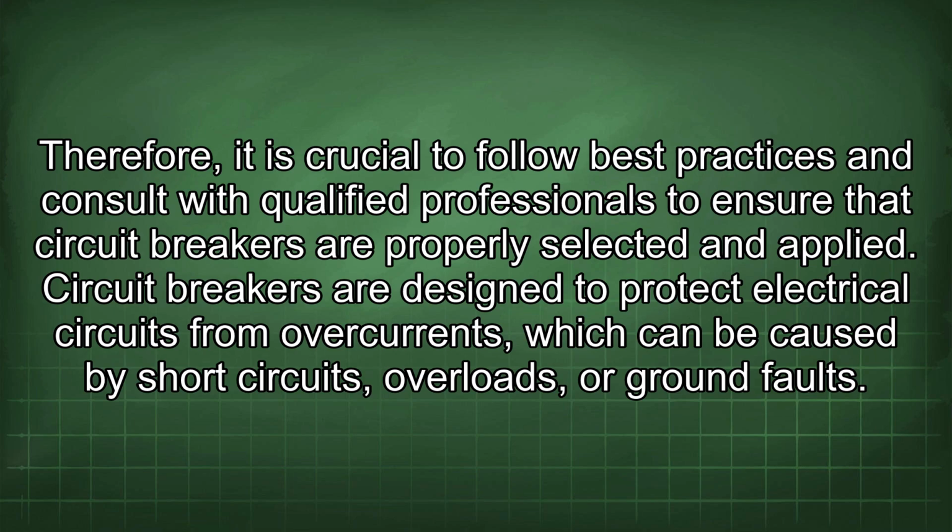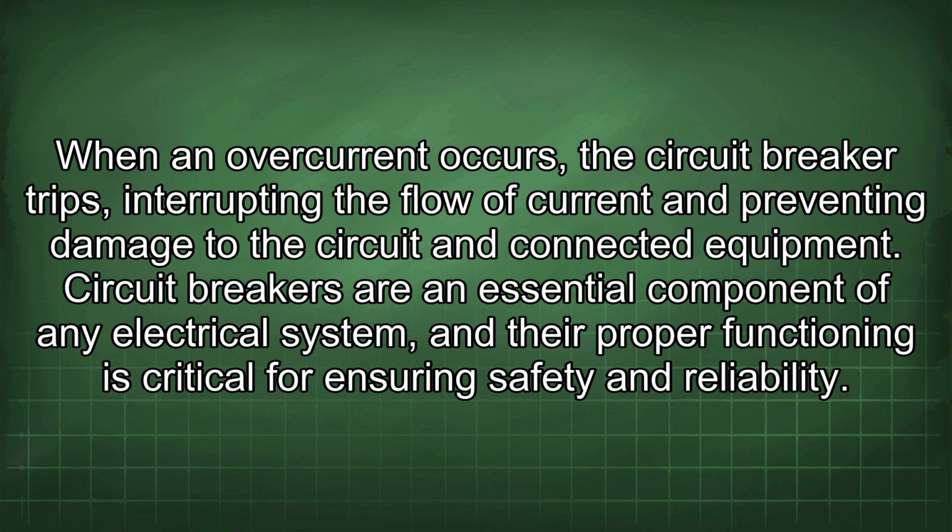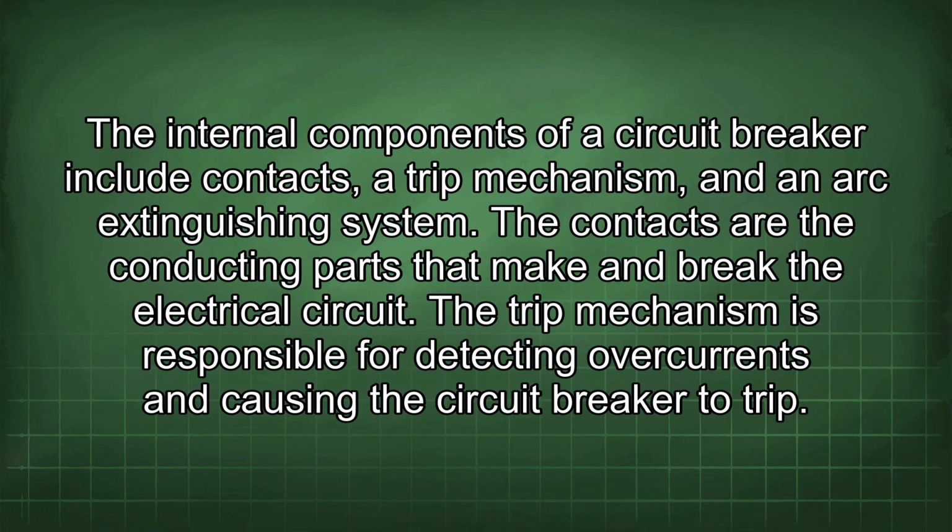selected and applied. Circuit breakers are designed to protect electrical circuits from overcurrents, which can be caused by short circuits, overloads, or ground faults. When an overcurrent occurs, the circuit breaker trips, interrupting the flow of current and preventing damage to the circuit and connected equipment. Circuit breakers are an essential component of any electrical system, and their proper functioning is critical for ensuring safety and reliability.